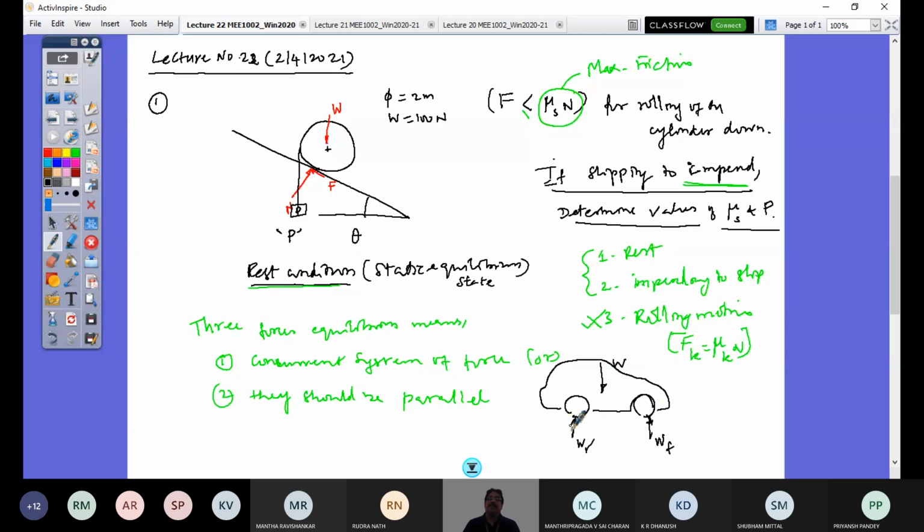So, 3-force equilibrium. The other example is the concurrent system of forces: whenever there are 3 forces in a free body diagram and that body is under equilibrium, there should be a concurrent system of forces. That is very common and evident. We have solved many problems, and in friction, wedge friction problems, you'll see that this is quite a useful approach to solve, right?